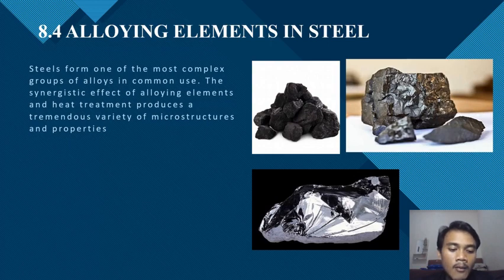Silicon is one of the principal deoxidizers used in steelmaking. Copper in appreciable amounts can be detrimental to hot working operations and has a moderate tendency to segregate. Chromium is generally added to steel to increase resistance to corrosion and oxidation, to increase hardenability, to improve high temperature strength, or to improve abrasion resistance in high carbon compositions.